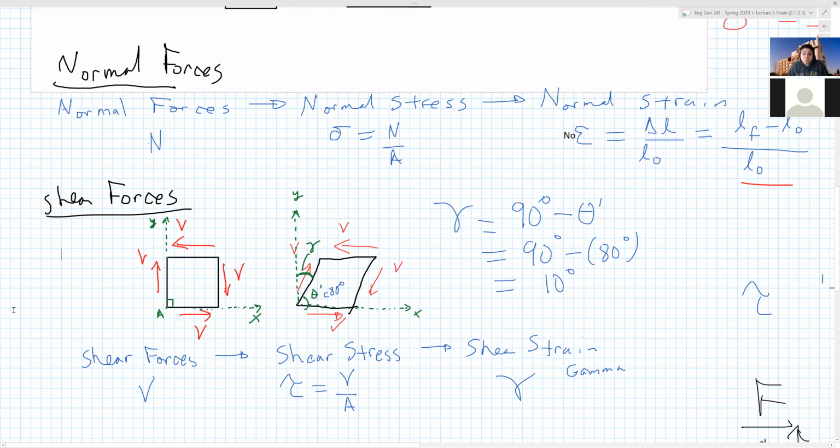Because of static equilibrium. If a force on the right side is down, you have to have an equal and opposite force up. But this is a force couple, so you need a force on the top side and an equal and opposite force on the bottom side, because don't you create a moment? And that's the unique thing about solid materials: when you shear them and let go, they'll bounce back.